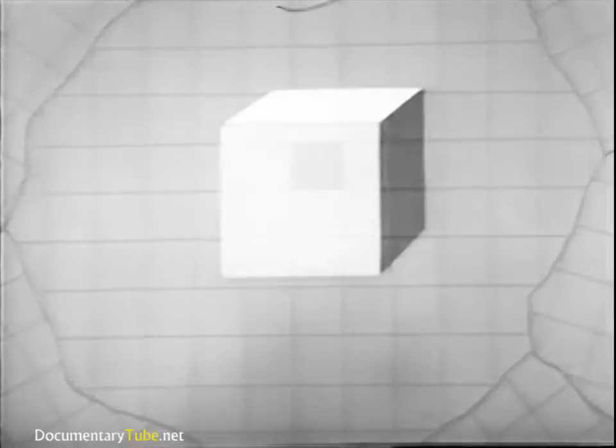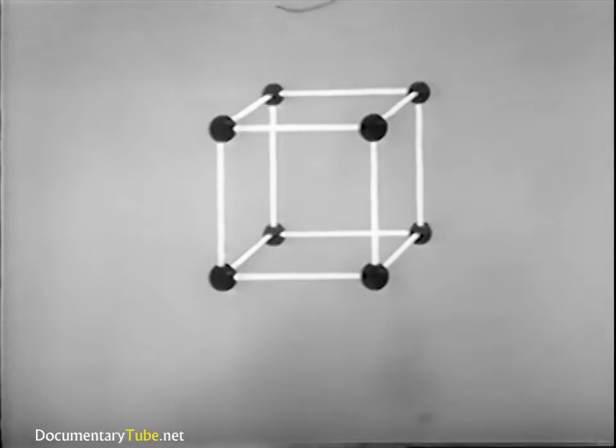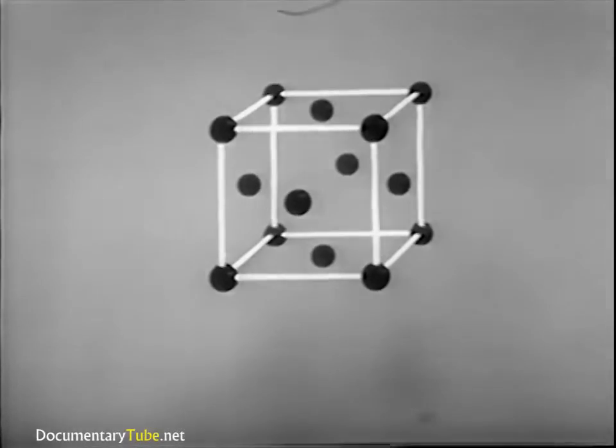The basis of this lies in the aluminum alloy itself. Microscopic study of a cross-section of an aluminum alloy specimen reveals a network formed by the boundaries between grains of the metal. Each grain is an accumulation of individual crystals or unit cells. The single crystal or unit cell is conceived to be cube-shaped with atoms of the metal arranged in regular order, one at each corner and one in the center of each face of the cube.